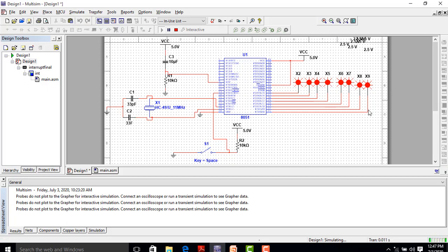Okay, by default, let's see. I'm pressing it the first time. Okay, so only this LED should glow, the rest of them should be 0. So it will indicate only 1. I'm pressing it. Let's see what happens. You can check it out. What happened? The first time, the interrupt has occurred. Let's press 2. Now this bit should become 1, and this should become 0, because in binary it will be 2 now. Press it. We get 2. Two times the interrupt has occurred.